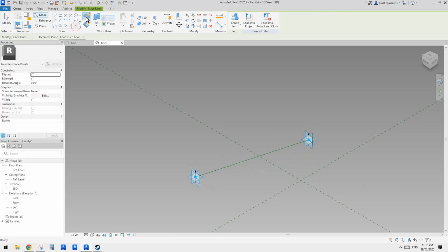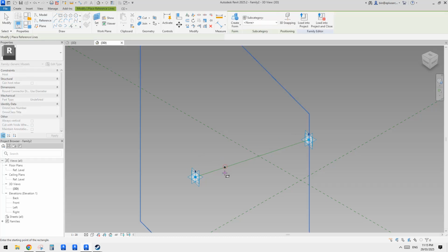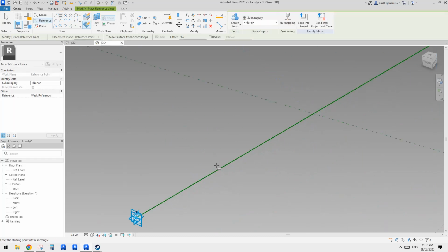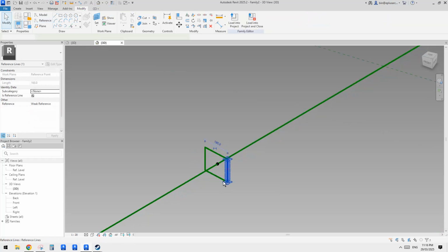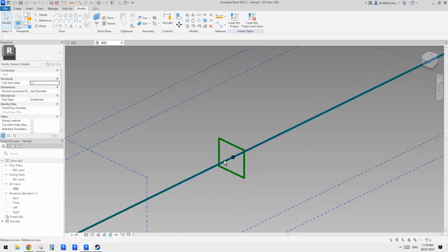And then place a point, use draw on face. Okay, and then we're going to just do a rectangular shape, use draw on work plane, set work plane, pick the vertical work plane on this point, and then we're just going to roughly create a shape, roughly a side. So actually we can make it parametric as well.